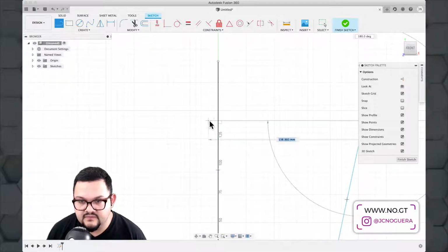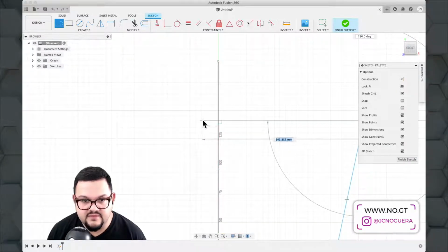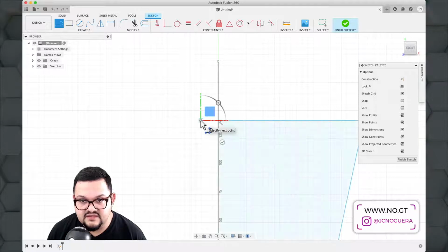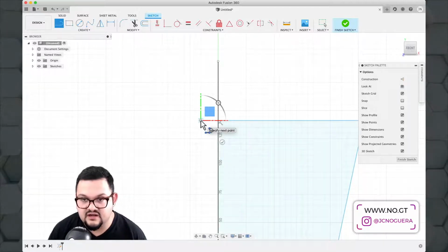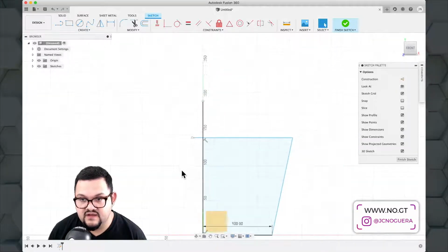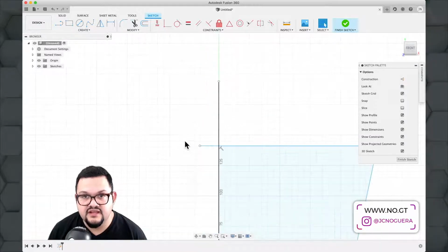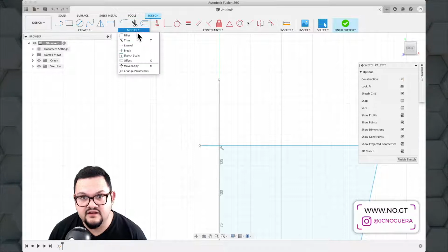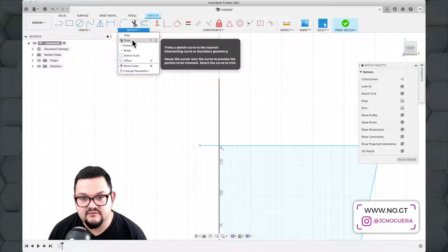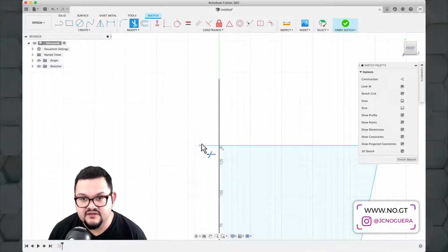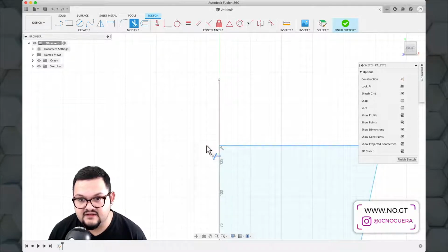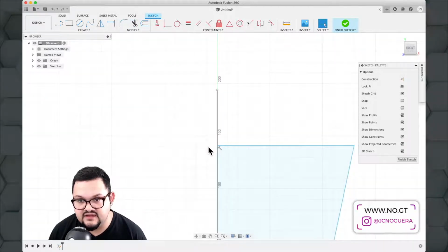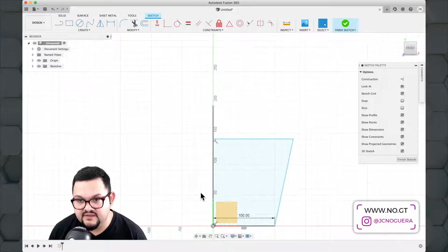Now, this is not going to find a snapping place for me here, but I can actually do this, and that'll give me a chance to talk about a different tool. So let's say you have a line here. You don't need all of it. You can actually trim this line to length. You can go to Modify here, select Trim, and then you can tap on this excess here, and it'll trim it back to where it needs to be.